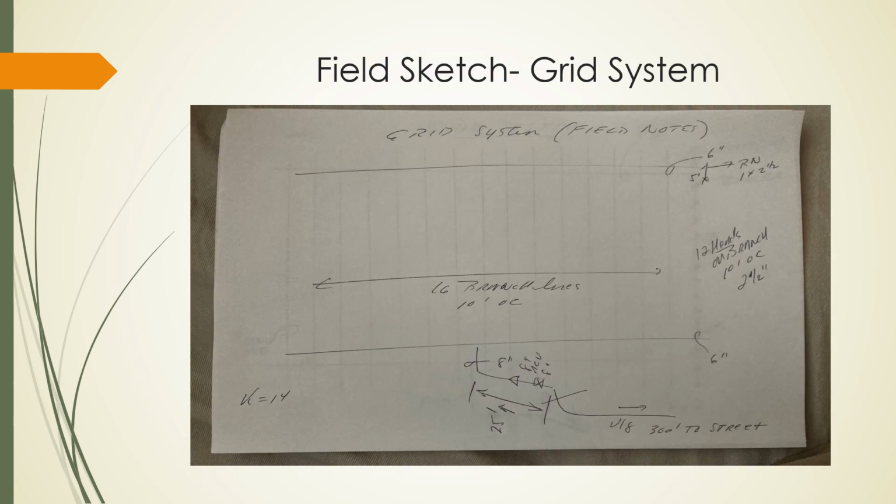Now it turns out the grid sketch is even easier. So what we're going to do is, again, get all that underground information: the riser height, the alarm check valve size, the control valve, et cetera, the size of the feed to the near main. And then we're going to grab the dimensions of the near main and the far main. Usually the near main is going to be one size larger than the far main. I just made them the same size for ease of purpose here.